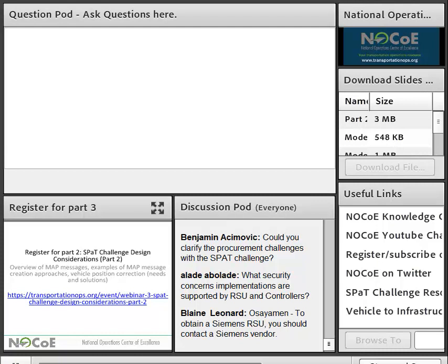For the left turn in the MAP message, you would be able to indicate that there's a movement for a left turn, and there would be a movement for through, for example. But in the SPaT message, you would only provide information about the through movement. The information about the left turn just would not appear in the SPaT message, indicating by default that it's not supported.